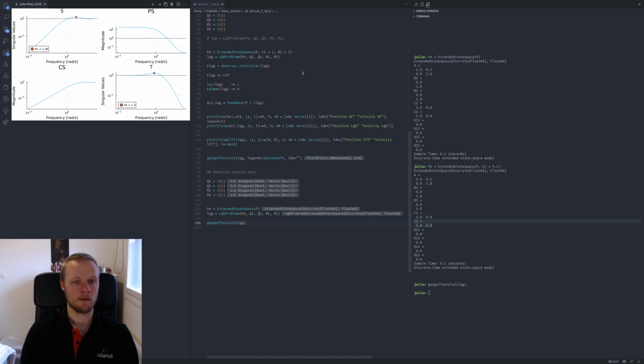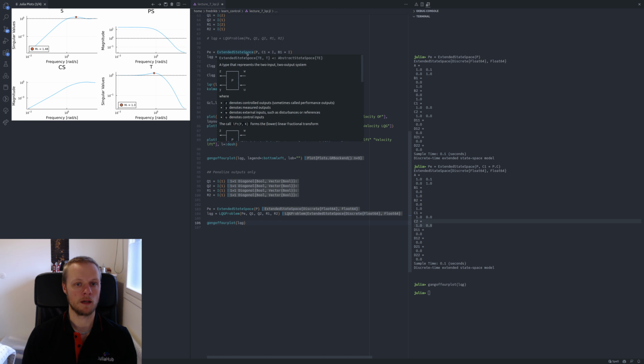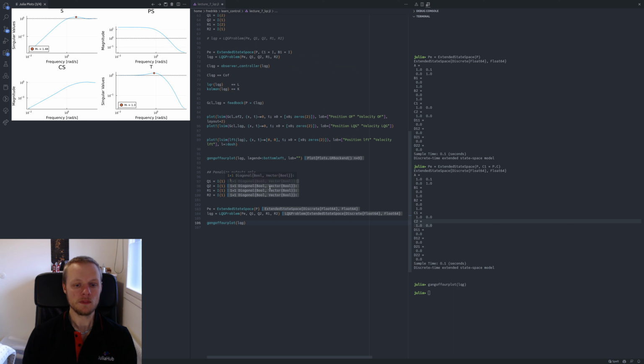So we have one feedback element acting on the position and one on the velocity, and velocity of course is the derivative of the position, so that's a PD controller. If we only penalize deviations in the position, then instead of a PD controller we now have a P controller only. So this is in fact, even though we use an LQG controller here, it corresponds exactly to a P controller.